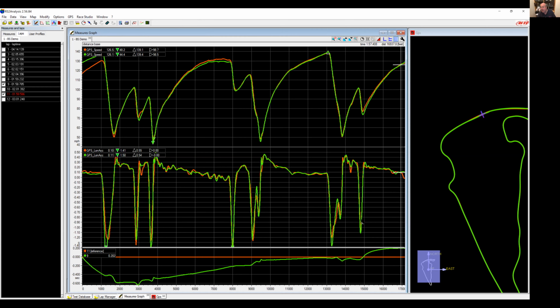He used exactly the same amount of brake. It was just throttle application, and we would have to look at the video to be sure, but the attitude and the heading of the car, this is why Race Studio 3 Analysis Beta is the answer to all my prayers. We're going to be able to look at the video and say, hey, he was pointed to the inside of the apex, and the car is set sail, and he can fully commit, which is what Andy Whittle wants his driver to do.